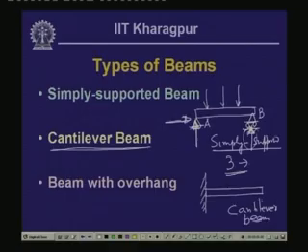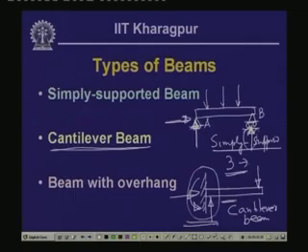Now, when this is subjected to load, at this support, as we have seen in the fixed support, it is expected that there will be three reactive forces generated. One is the vertical force, one is the horizontal force, and another one is the moment. So, these three reactive forces will be generated at this support, and again if we look into this particular member, since we have three reactive forces, these can be evaluated using equations of statics, and hence this member also is a statically determinate member.